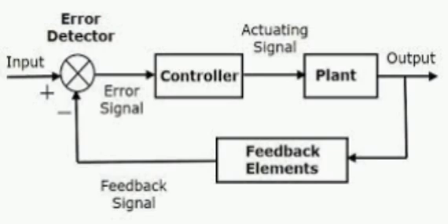In the series RLC circuit, omega n equal to 1 by root LC, zeta equal to R by 2 into root over C by L. In the parallel RLC circuit, omega n equal to 1 by root LC, where zeta equal to 1 by 2R into root over L by C. In the translational system, zeta equal to F by 2 root KM. In the rotational system, zeta equal to F by 2 root KJ.